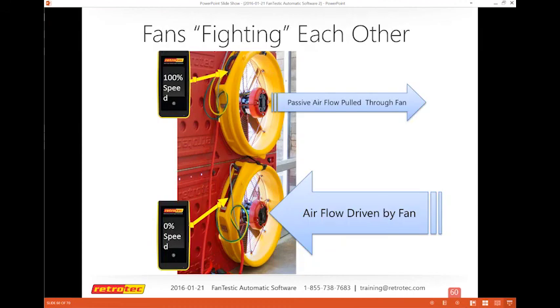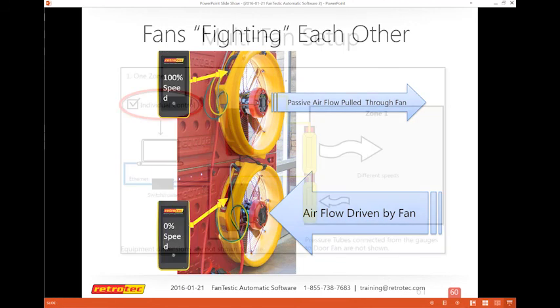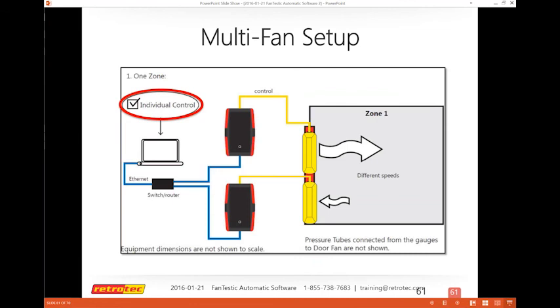And here you can conceive just from the scenario that one fan starts much sooner than the other, and it can actually be going negative. It can be drawing more air out of it, backwards the wrong way, than what you'd started. These are some slides that I brought up when Colin started to talk, and these are individually controlled, individually wired, and one fan can actually overpower the other. It's not that uncommon that it takes anywhere from 30 seconds to a couple minutes, and the other one begins to slow down and can actually go backwards.